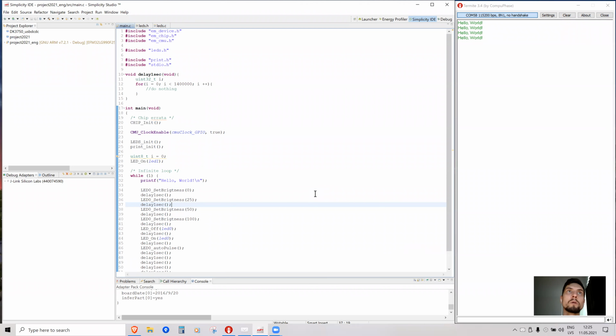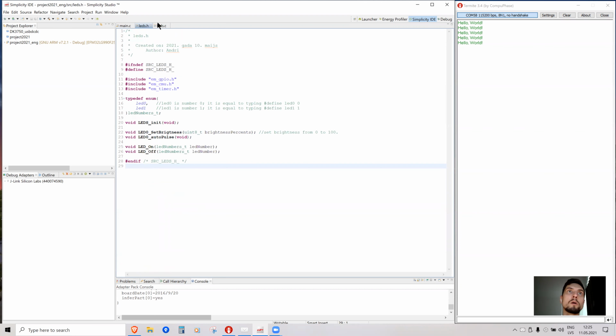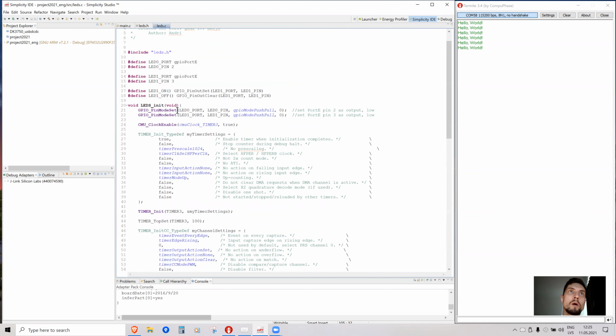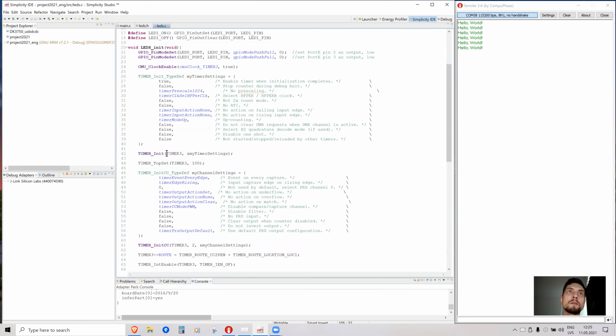In this lab, we will test out the microcontroller's capability to run at low energy, meaning a couple of microamps instead of several milliamps, and using the real-time clock to accomplish this goal. So last time we worked with a regular timer or clock, whatever you call it, timer counter. And there's this limitation for almost all microcontrollers that the timers, which are timer peripherals, take their clock source from the same source that is used by the CPU.